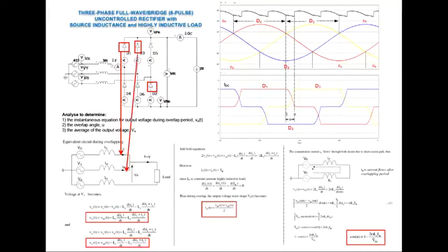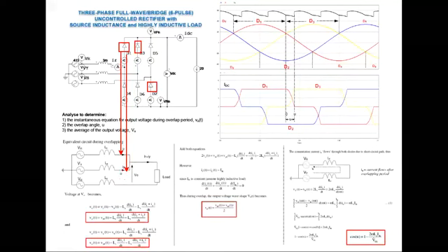And for the yellow phase, D3 is also a short circuit, and we have a current IY flowing through it. And here we have D2 as a short circuit. We can have IDC that flows back through ID2, or we can have the summation of IR plus IY flowing through the output, which equals IDC flowing through D2. So this equivalent circuit represents the whole rectifier during the overlapping period.